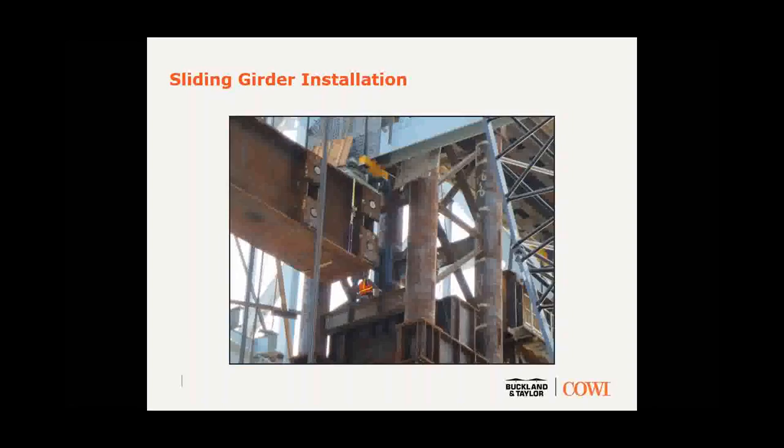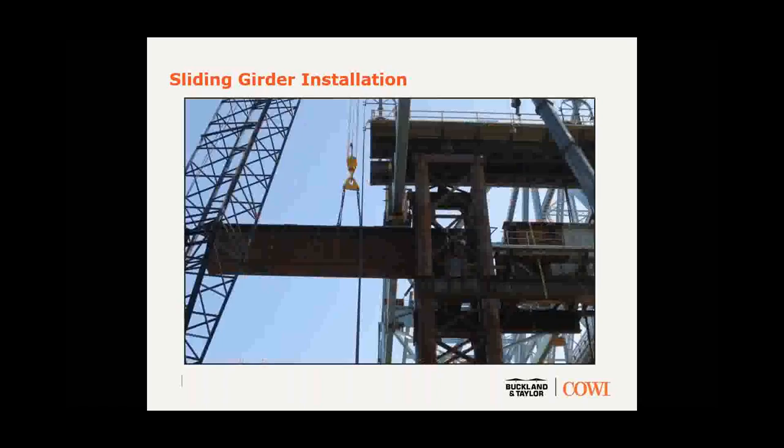And there's your four moment connection pins, and that end of the girder about to slide into the hole. There's a worker there, you can see the scale. And once it's gone in as far as the crane can reach, that is, before the tackle starts to foul the structure, we basically blocked it off against the towers here and here and let it go. So it became an unconnected cantilever, basically, with an upthrust reaction here and a downthrust reaction here, at which point workers could go out on the sliding girder and disconnect the crane.